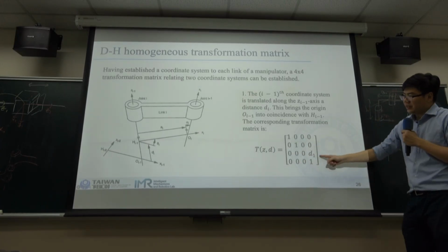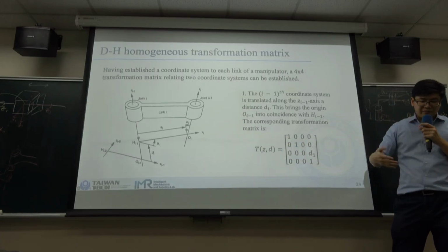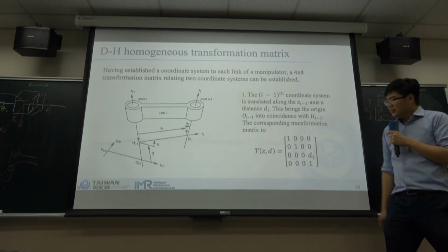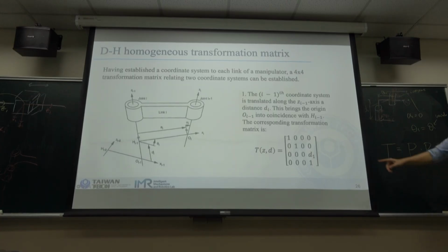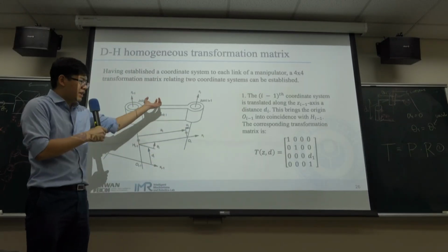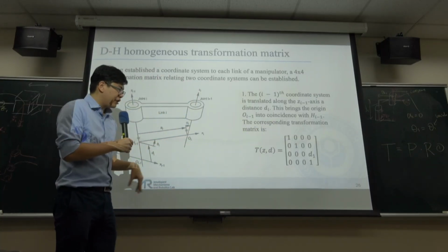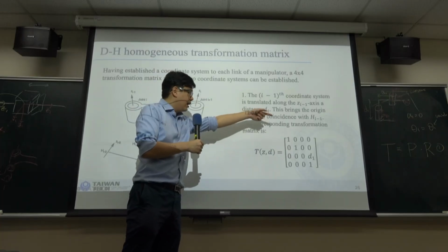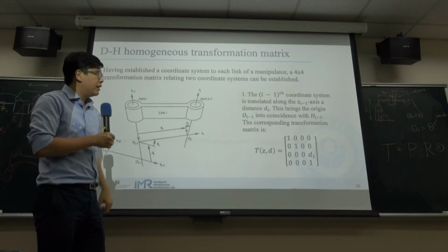So we start with the d. So the z-axis will be done first, then the x-axis. So we'll have d. So we can separate the DH parameters into 4 homogeneous transformations. It's the 4 parameters: the d and the theta and a and alpha.